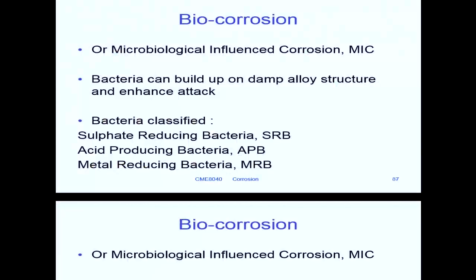And as you can see, there's a substantial amount of marine life attached to this boiler, and that is inducing corrosion underneath the surface layer of bacteria and algae, and that's what we're going to talk about next. We're going to talk about biocorrosion, or microbially induced corrosion.